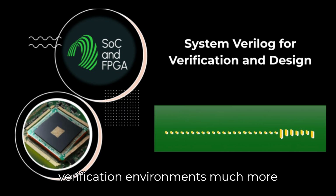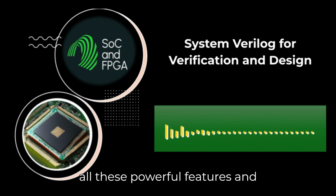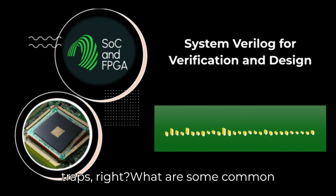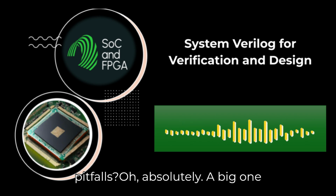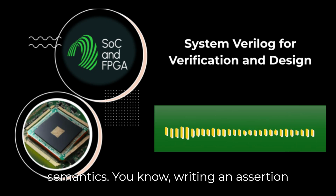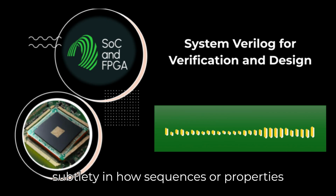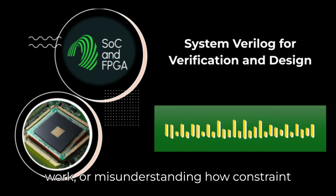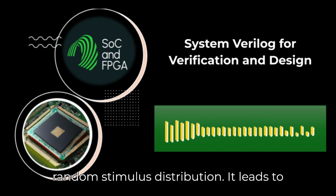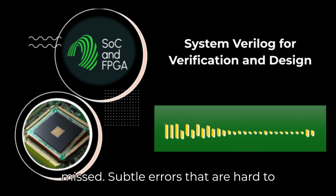These patterns make your verification environments much more extensible and maintainable. Even with all these powerful features and guidelines, engineers can still fall into traps, right? What are some common pitfalls? Oh, absolutely. A big one is just misinterpreting the language semantics. Writing an assertion that looks right but doesn't actually check what you intended due to some subtlety in how sequences or properties work, or misunderstanding how constraint solver probabilities might affect your random stimulus distribution. It leads to wrong functionality being tested or missed. Subtle errors that are hard to spot.